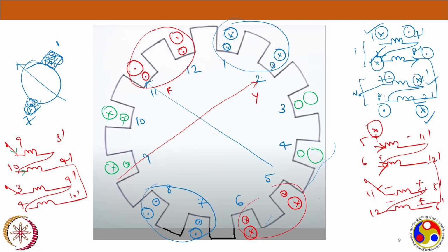Easy current to see the current distribution, that's it. So then the 3 and 4 will have the dots. These will form one combined coil group. And if you see the current distribution and the resultant phase of B phase, right hand thumb rule, it will go downwards. This is the B phase.